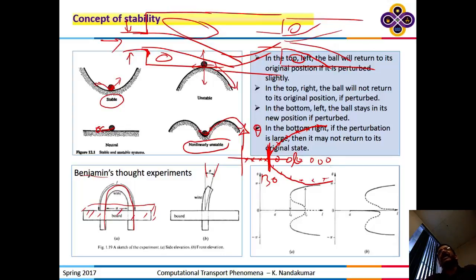In a numerical way, you can ask the question, why does it flip from one to the other? The round-off errors in numerical calculations can produce enough disturbance. So it is linearly unstable, so the disturbances grow. Depending on how well you have machined these, you can delay the transition. Once you exceed that, soon enough, you will have this transition. If the machining is so perfect, you can delay that for a while. But the inherent instability is in the equations. So all it needs is the growth of the minor imperfections.